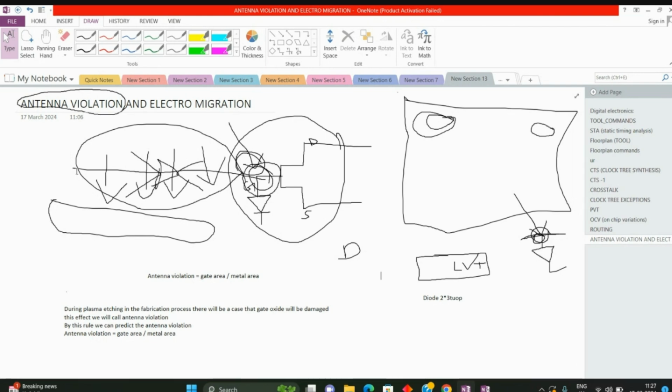If the net is normal, it is not causing any delays and the net length is proper, then only we go to the fixing method of antenna diode. These questions will also come in the interview. Just knowing the antenna violation theory will be okay, but logically there will be some other kinds of questions also.